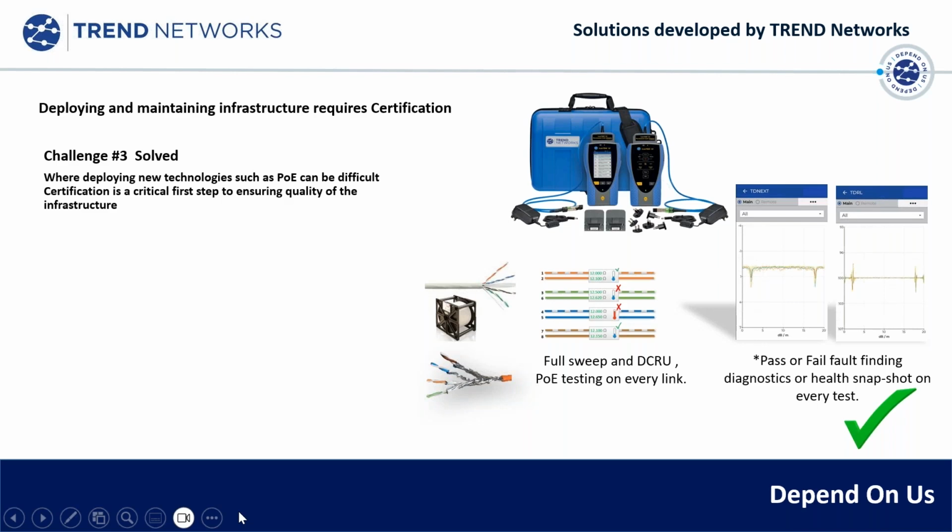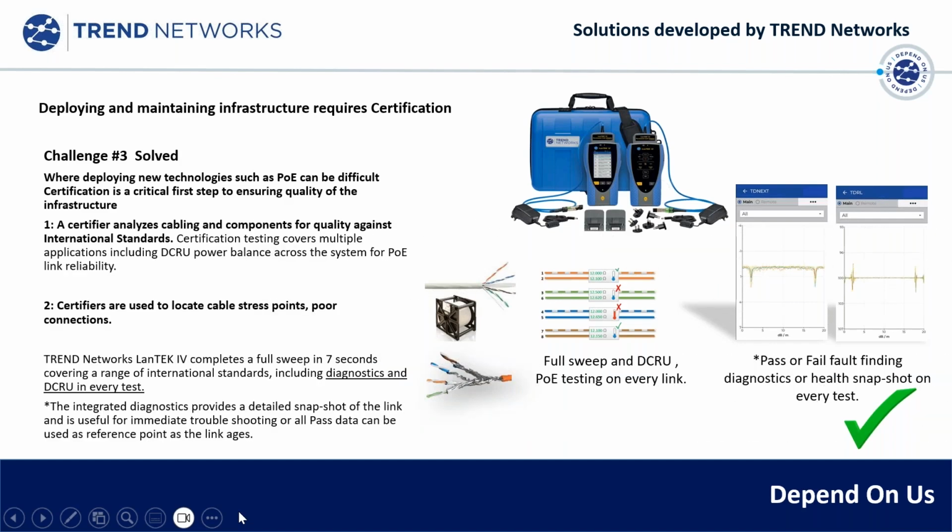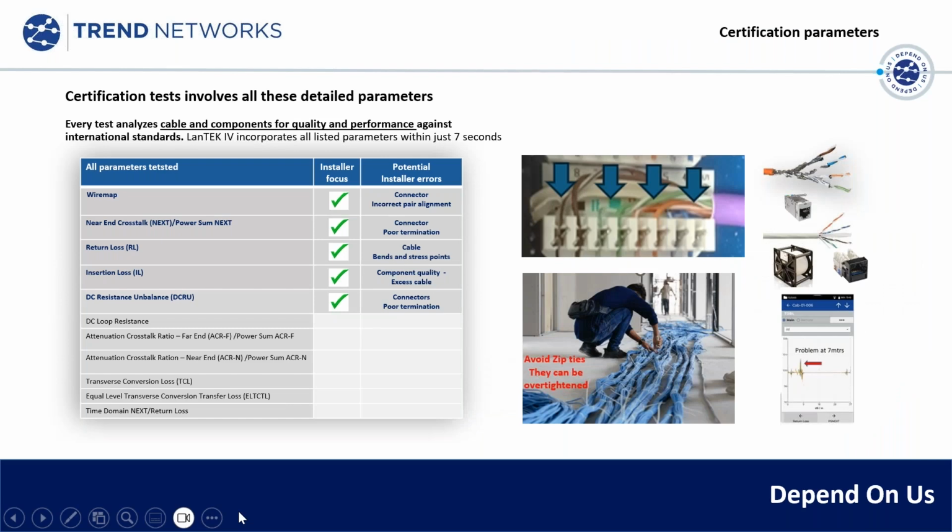And the reason for that is it's the most comprehensive test to a standard that you can achieve for quality of the connector and the connected cable and the total link performance. So certifiers are actually analyzers that do the best performance test you can achieve to optimize your network performance. I've now just put on screen some of the tick boxes that a certifier must do. And the important thing there is it's looking at it as a qualitative test. So verifiers again are important, everybody needs one, but you must have a certifier for qualitative testing.